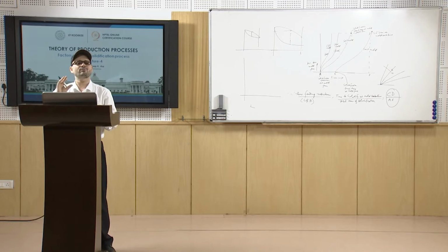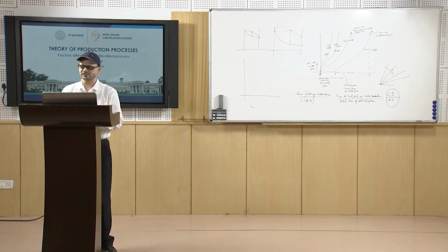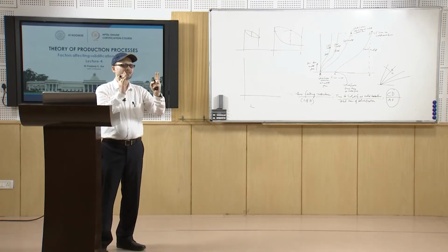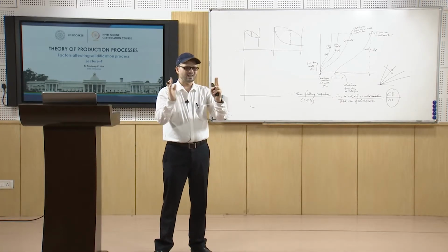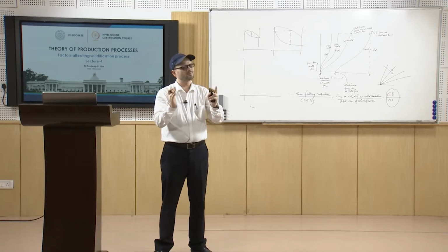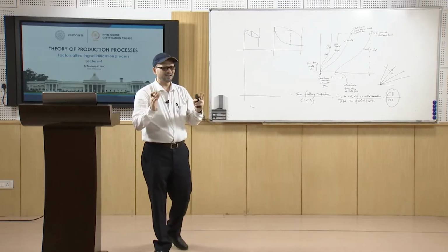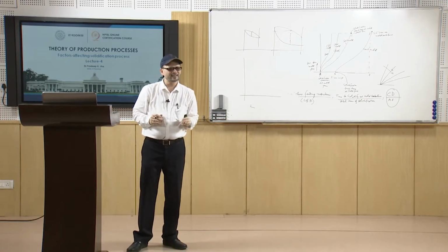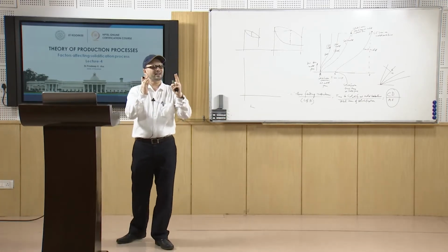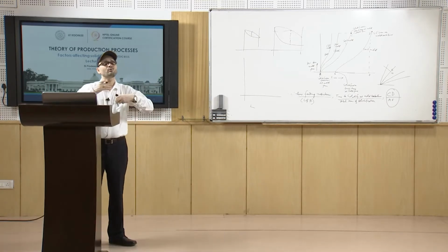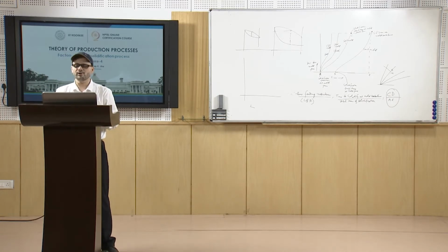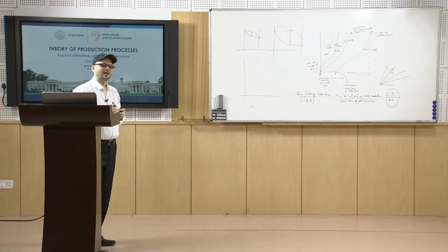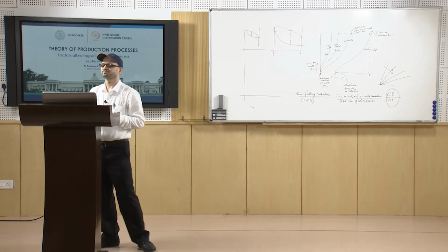Similarly, in the case of a sand mold, heat removal rates are increased by a decrease in the mold thickness. In the case of a chill mold, if you have larger thickness values, the amount of heat extracted will be more, but not beyond a certain point. Similarly, in the case of a sand mold, if you decrease the thickness, the heat extraction will be more. So, it will be increased by decreasing the mold thickness below a certain thickness. Above this thickness there is little effect.